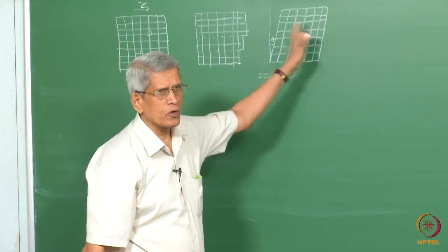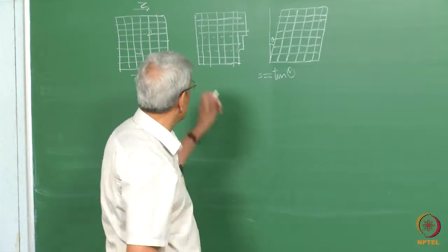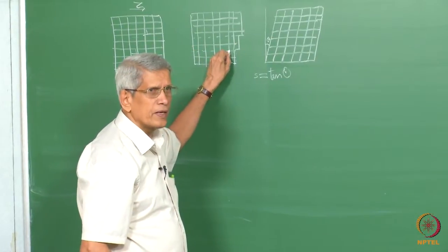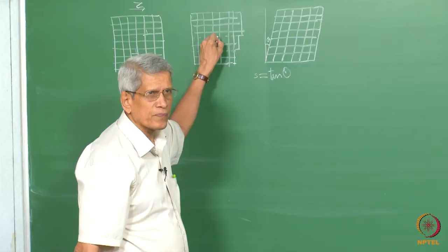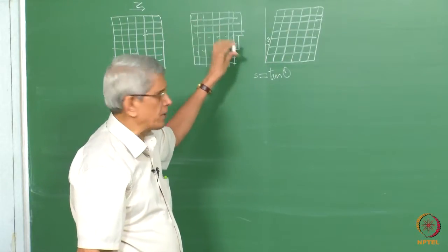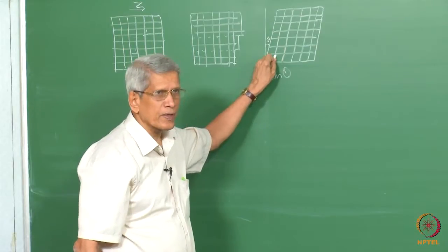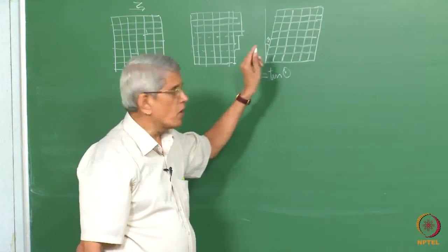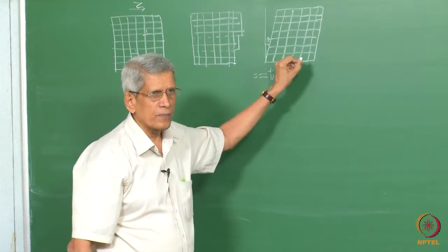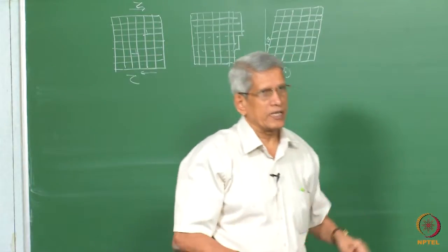Every unit cell also has undergone a deformation, whereas here, by this movement, the crystal structure is being preserved, correct? Once the dislocation has gone through, nothing has happened, whereas here there is shape change for a particular angle of shear, and the shape change occurs in such a way that the crystal structure is being retained.